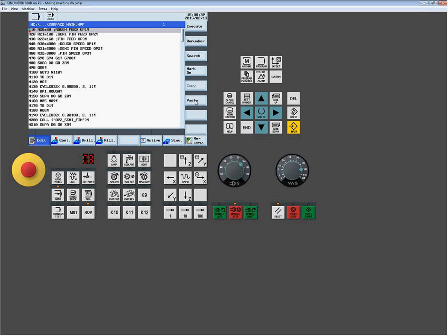Well, I'm going to do all my tool changes in here. I'm going to set up my high-speed technology statements here. I'm going to call up whatever the programs are from here. I'm going to do my safe retract axes, my shut-offs, all I can set up in the main. What I'm really leaving the part program up for, which now is a subprogram call, is simply going to be my cutter path, allowing the CAD system to do what it does best, which is output cutter path.